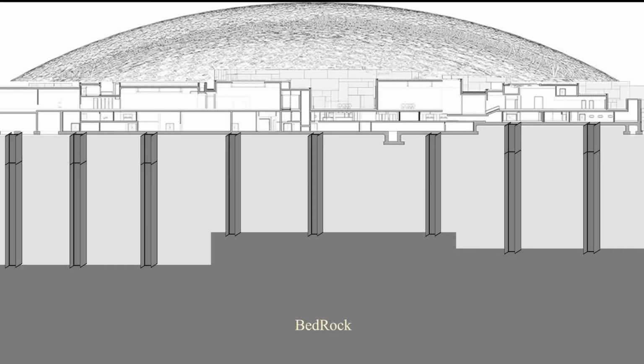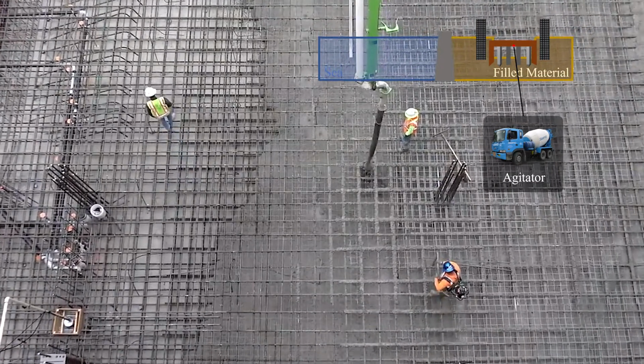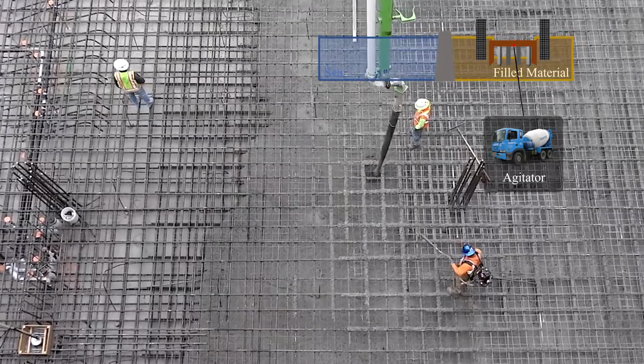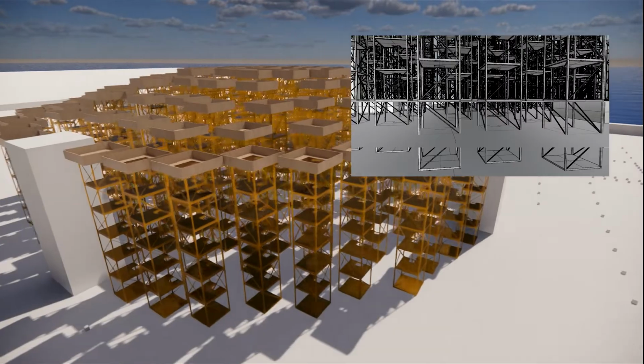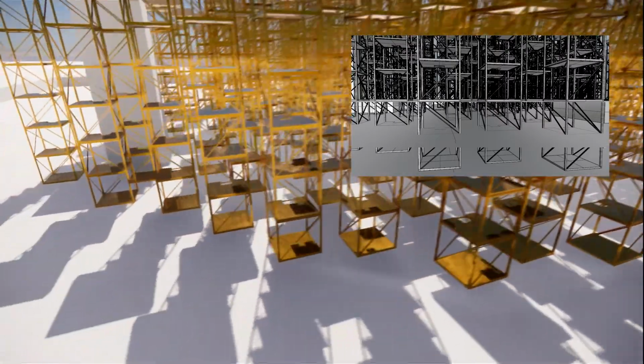It is useful on Saadiyat Island, where the depth of the bedrock varies. After all the foundation piles were built on the excavated ground, concrete was placed to make the raft slab. The raft slab was first placed at a depth of 7 meters, and after that, a temporary steel tower was built.